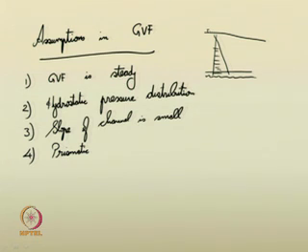So, that prismatic condition has to be maintained. We are also suggesting that the roughness coefficient is the same. It is not varying with respect to depth of flow. It is constant for the problem. So, based on these assumptions, one can start to analyze the gradually varied flow.